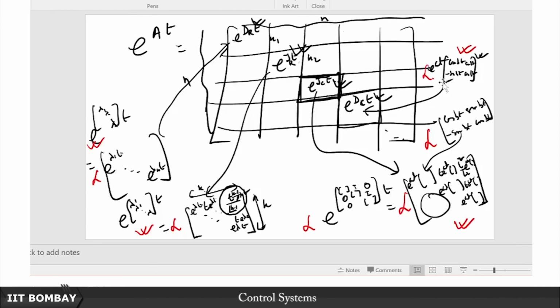So of course now you might say, well, what is the guarantee that you might not have picked this last one, but they might have cancelled each other out in some weird way? So what is the proof? But remember, we already proved that earlier. We started this lecture with the proof that if you have a jointly controllable and observable realization, we use that older result, that CA to the power K B in one realization must be equal to CA to the power K B in another realization, irrespective of the size of the two realizations. So we assumed that some realization is jointly controllable and observable, and then we assumed that there exists another realization of a smaller size which leads to the same transfer function. In other words, this jointly controllable and observable realization fails to be minimal, and then we showed the contradiction.